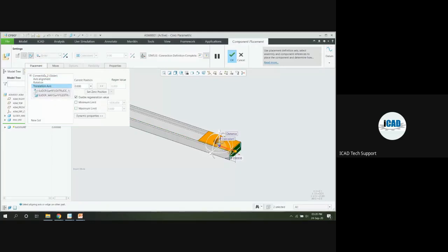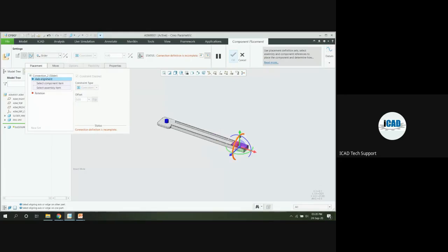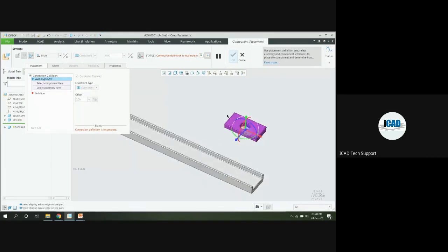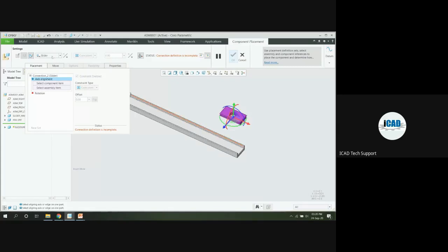Okay. So I am deleting this constraint type, and now you can see all the degrees of freedom of my model are available. Here, in the user defined drop down list, you can see rigid, pin, slider, cylinder, planar, ball, weld, bearing, general, 6 degrees of freedom, gimbal, and slot. I will show how we can use each mechanism, starting with some of them.